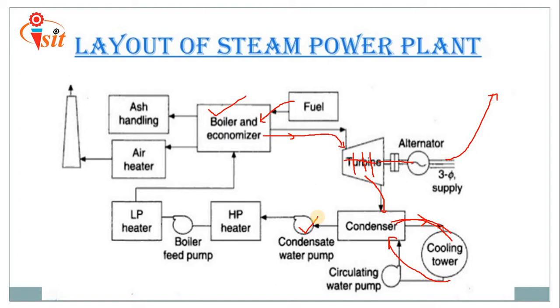There are many types of condenser where we need not use a condensate extraction pump, like the ejector type condenser, and the barometric condenser, where there is no need of adding a condensate extraction pump.